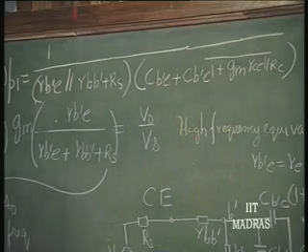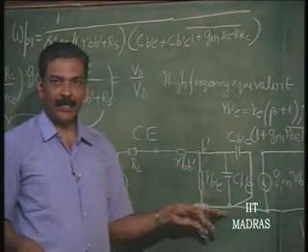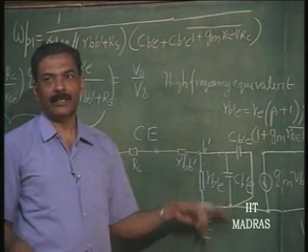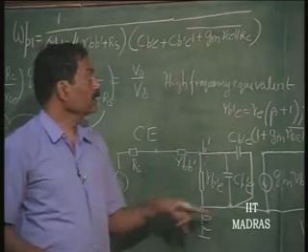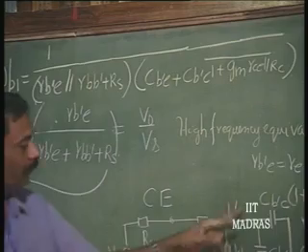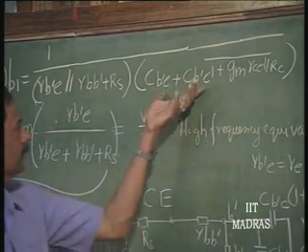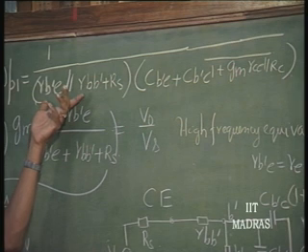That can be written by observation. Always find out the net capacitance and the net resistance across the capacitance. That will determine the time constant at any point. Okay. So, C B dash E plus C B dash C into 1 plus G M R C parallel R C E is the net capacitance. Across that capacitance, we have a resistance of R B dash E parallel R B B dash plus R S.